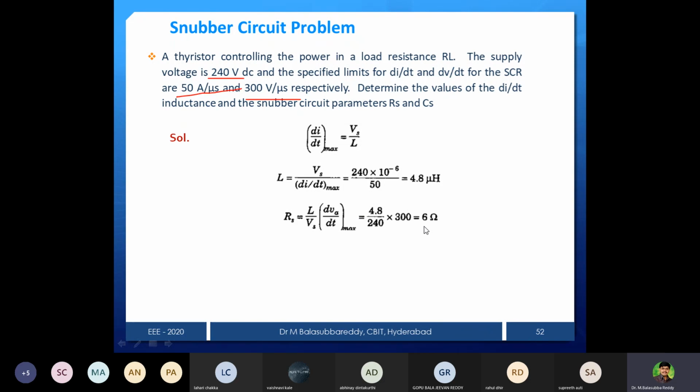And finally, we need to find what is the Cs. So that will be the empirical relation as I mentioned. Rs is equal to 2 delta root L by C, or Cs. That Cs will be unknown. And delta we have to choose a value between 0.5 to 1. And therefore, for the optimal value, delta is 0.65 as they mention in the derivation.